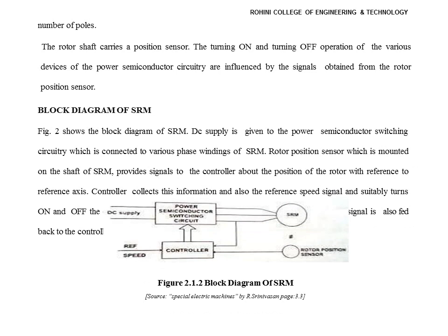The rotor carries the position sensor. The turning on or off of the various devices of the power semiconductor circuits is influenced by signals obtained from the rotor position sensor. This is a block diagram of the SRM. SRM is nothing but switched reluctance motor.